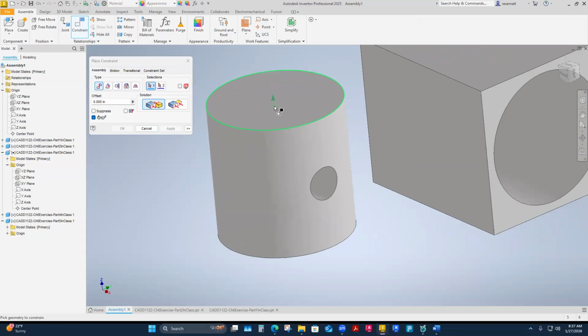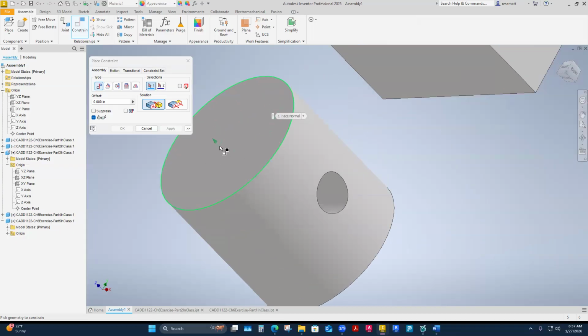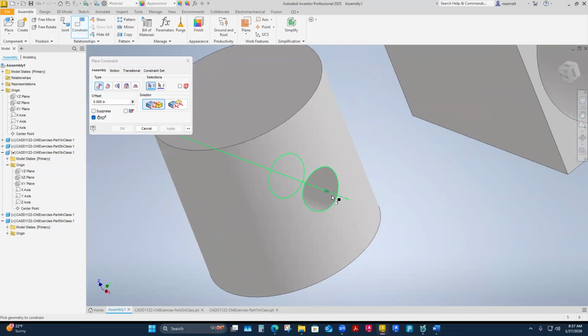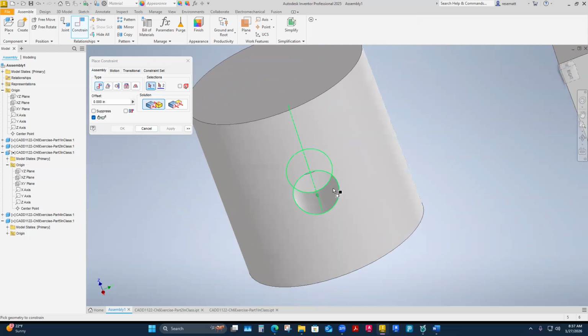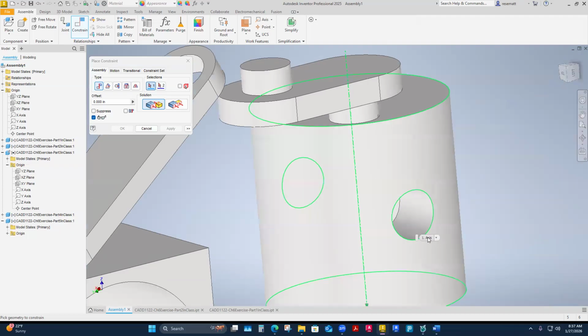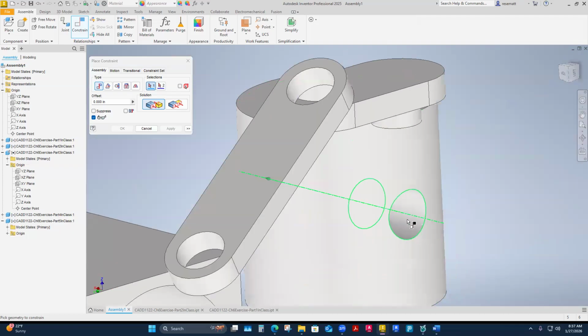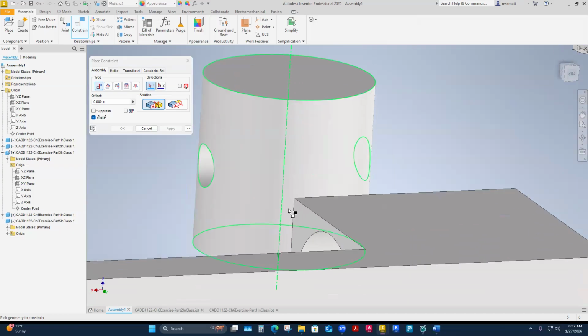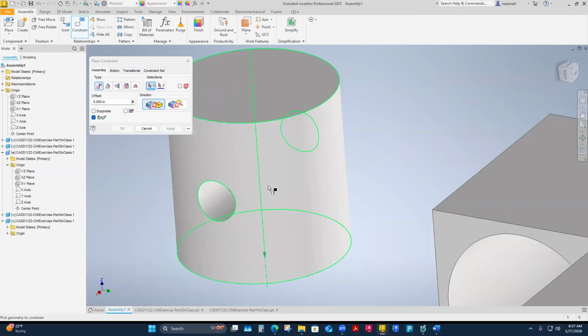This is me selecting this surface as a potential thing to constrain to something. I could choose this axis of this hole here that shows up. It shines the edges of my feature, but then it shows this axis, and it even has a directional arrow on the axis if you look at it here. To switch that directional arrow, I don't always know if I can just hover. I don't think so. I think it has this preloaded directional arrow that way.